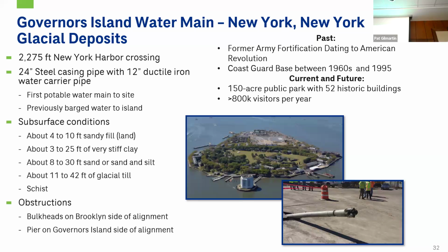So, yeah, it was along a tangent. So we made sure whenever you're doing HDD, general rule of thumb is you want at least one pipe stick in before you start making a curve. You can do horizontal curves, and very experienced contractors can potentially do that. But in general, we want to separate our horizontal from our vertical curves, or horizontal from horizontal.